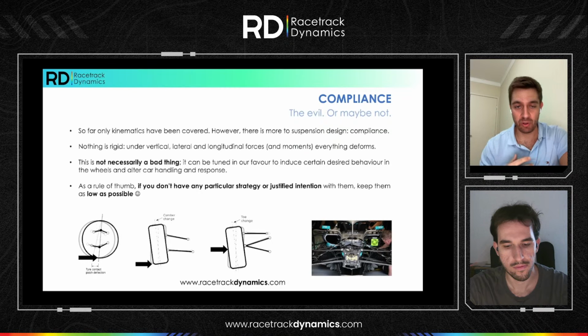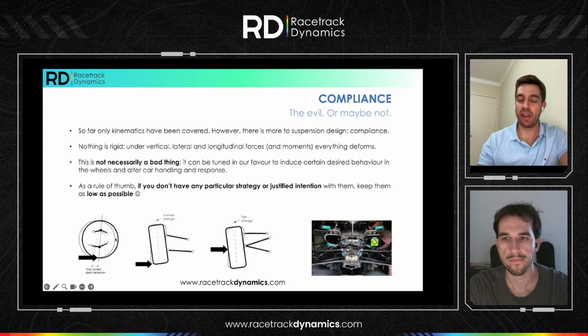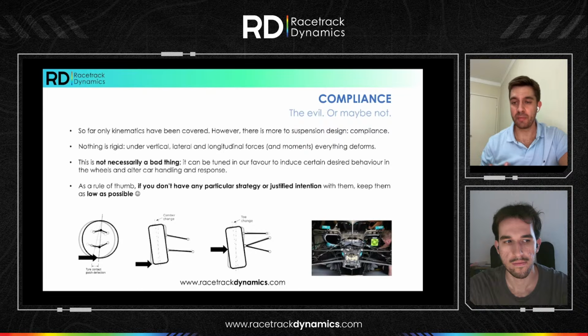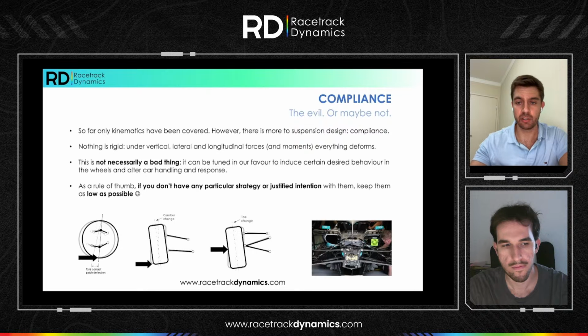So as a rule of thumb, and what I always say in formal student competitions, compliance is not necessarily bad if you have a particular strategy. If you don't have any particular strategy or justified intention, then yes, you need to keep it as low as you can. This is my rule of thumb. So everything is going to deform. At the bare minimum, I like to talk about what I consider the four more dominant compliance metrics, which are steer and camber for braking, and for lateral, for cornering. So these are the very minimum that we need to understand in our car.